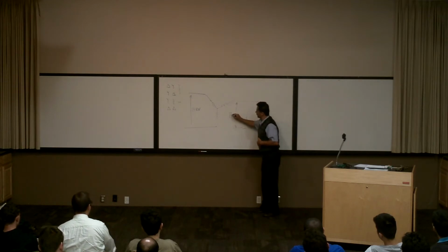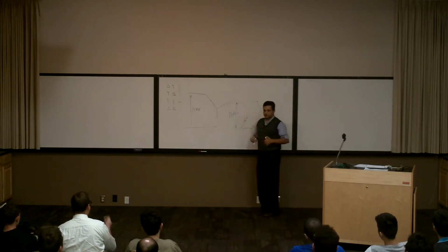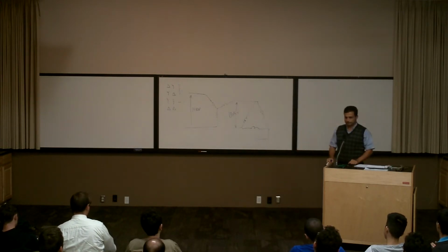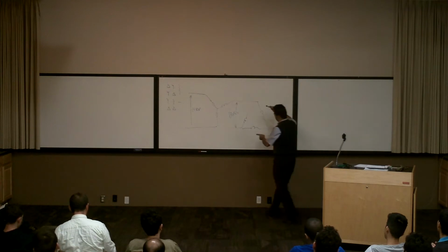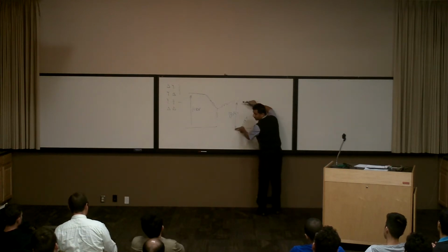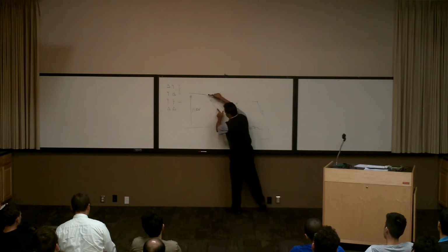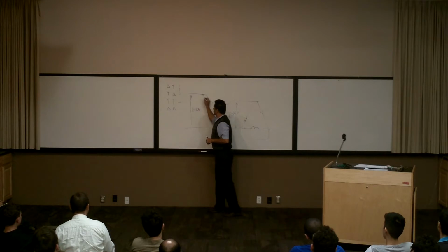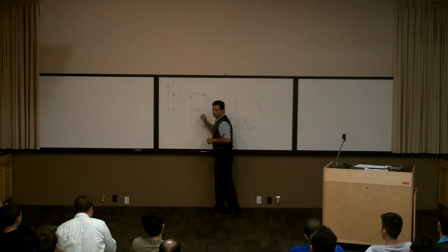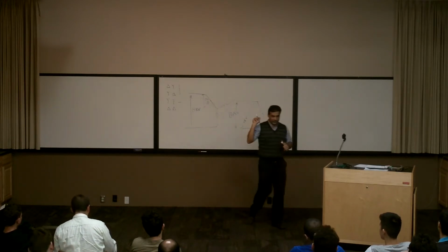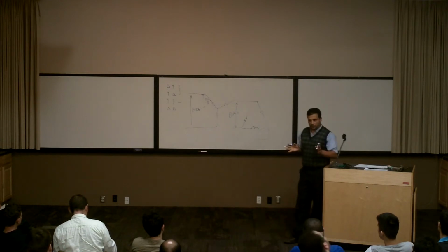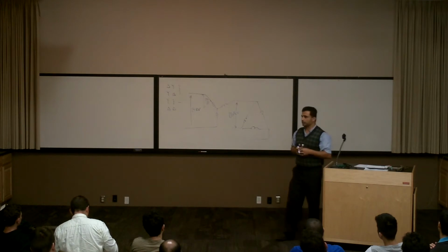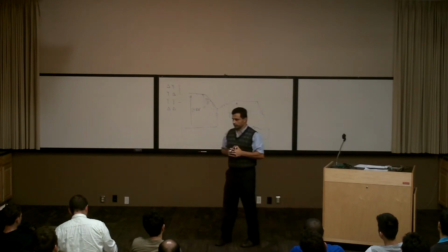Can you see what's the difference between these two? What is the main difference between these two? How much is the voltage over this one? 130 kV, right? How much voltage should this one go? How much is this one? 130 over the square root of 3, right? So, with a star connection, the voltage across the one winding will be not half, but maybe about 60% of what it is with the delta connection, right?